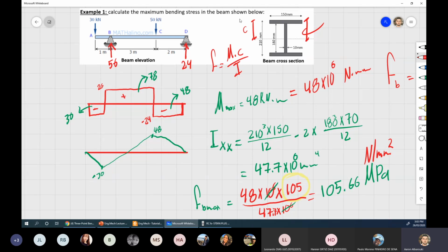But for this particular cross-section and these forces, I can use 200 MPa steel and that will be okay. This down the track will be your advice as an engineer to quantify a size and type of steel to be used for design scenarios.